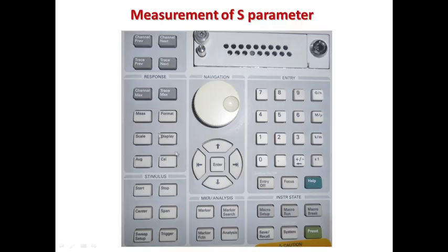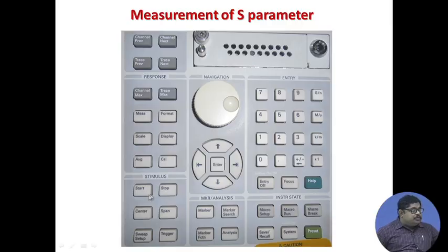So, you can select the start and stop, so that you can get the frequency. Similarly, you can sweep, which means the frequency you can vary, then you can give a trigger. This is like when some event occurs, at that time I want to measure; that is called a trigger. Then you can put markers, so that exact measurement values automatically come; those are called markers.